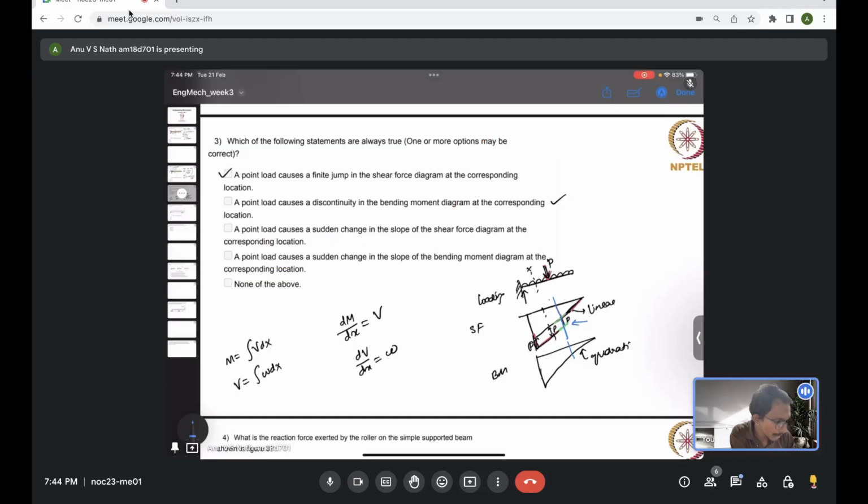Now if you take another section here, the extra area getting added to the previous shear force diagram, changed a little bit because of the extra force, gives the extra moment, which is the area under this region that I have marked in green color.